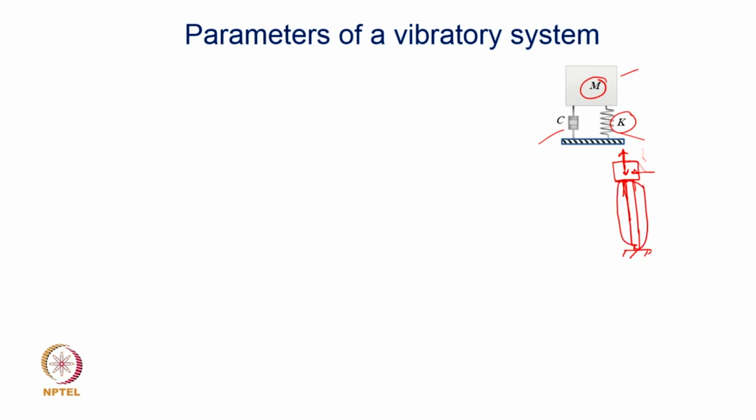Okay. And where is the dashpot? The dashpot does not appear here physically, but later on, as we will know when we discuss damping in more detail, the very elastic deflection generates a dissipating force, and the dissipation mechanism in a stretched body actually generates a damping effect, and therefore, the same column acts like both a stiffness as well as a damping. Okay. But these are the elements, so what are those parameters? How do I find k? How do I find m? How do I find c?